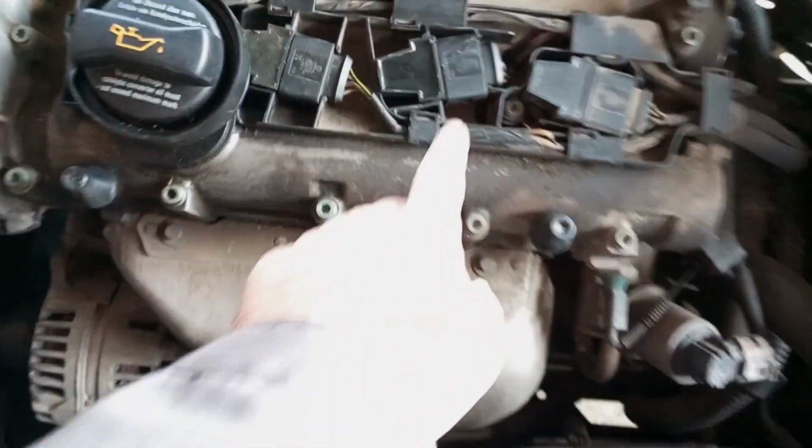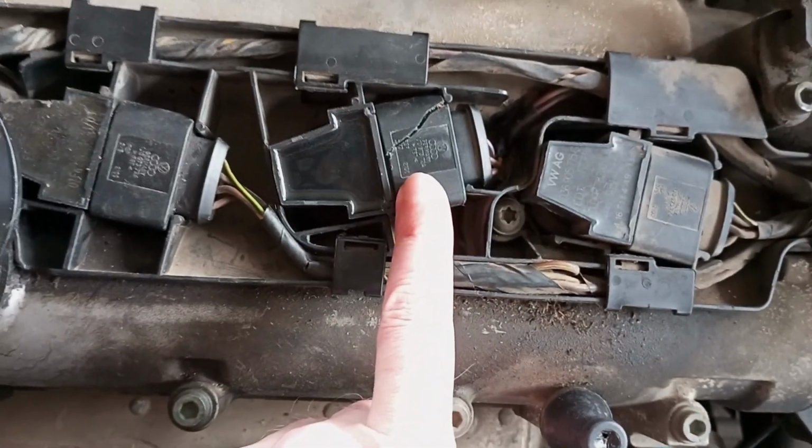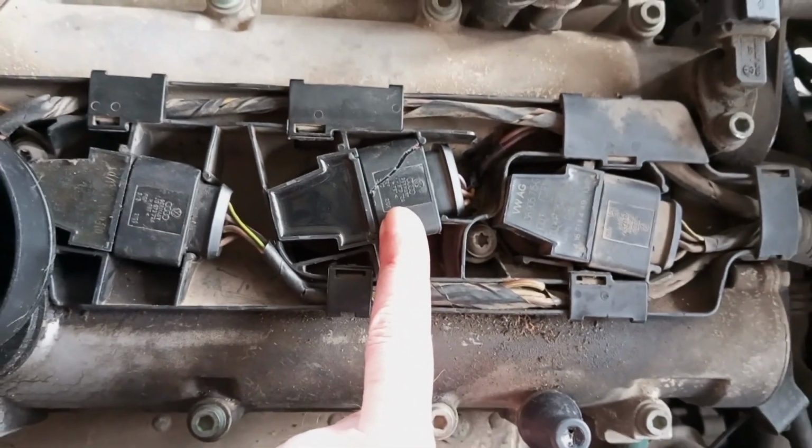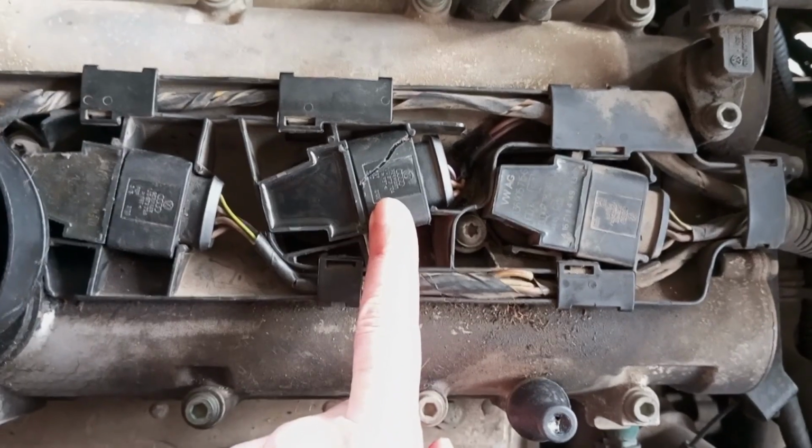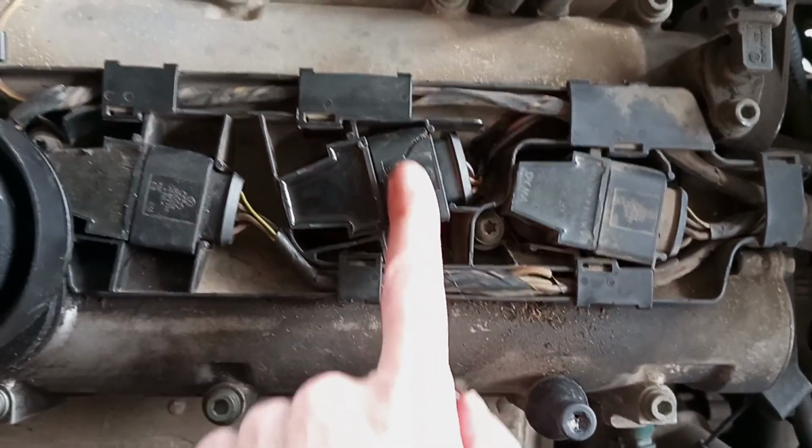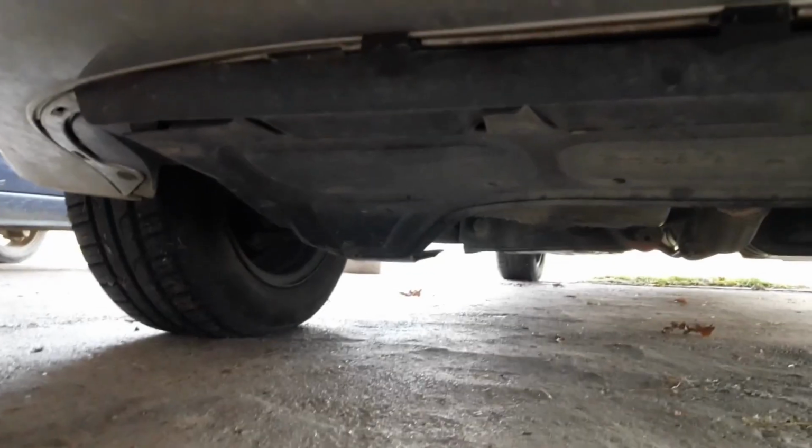I'll make, again, a very simple example. If the OBD tool tells you it's an ignition coil, I'll take that example again. Check the connector, check the wiring, you know, just take a look around the engine. If you have a suspension problem and you suspect that the knocking is coming from one place, always check the other components, okay? What I'm trying to say, always have a wider perspective when diagnosing a car problem. Don't just blindly look at one thing, but look at the whole system.